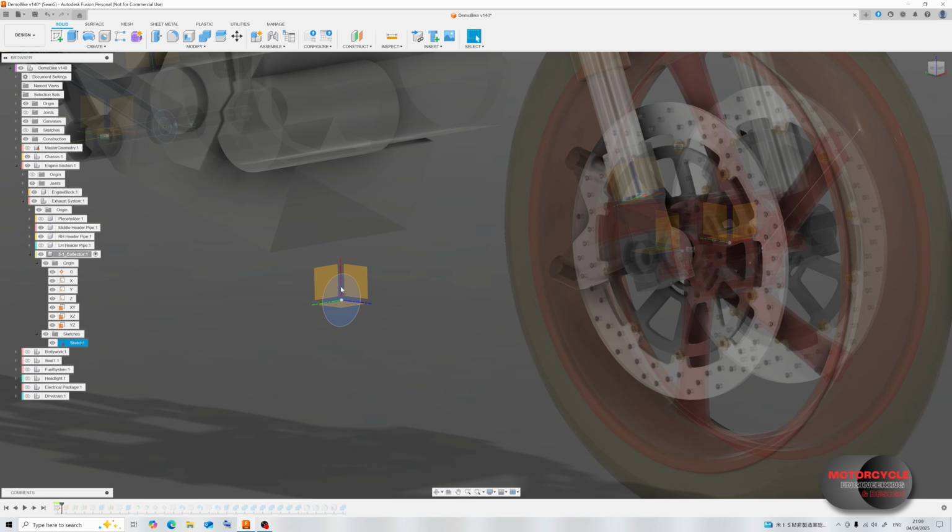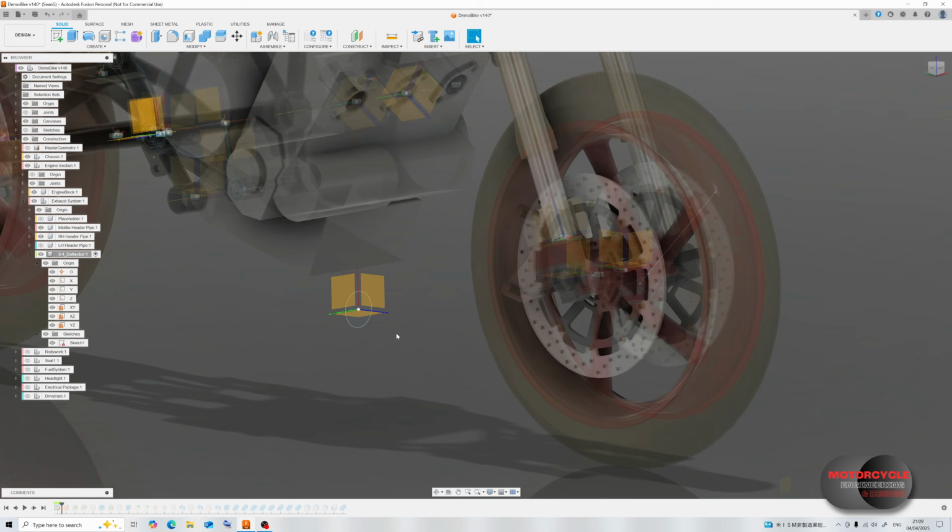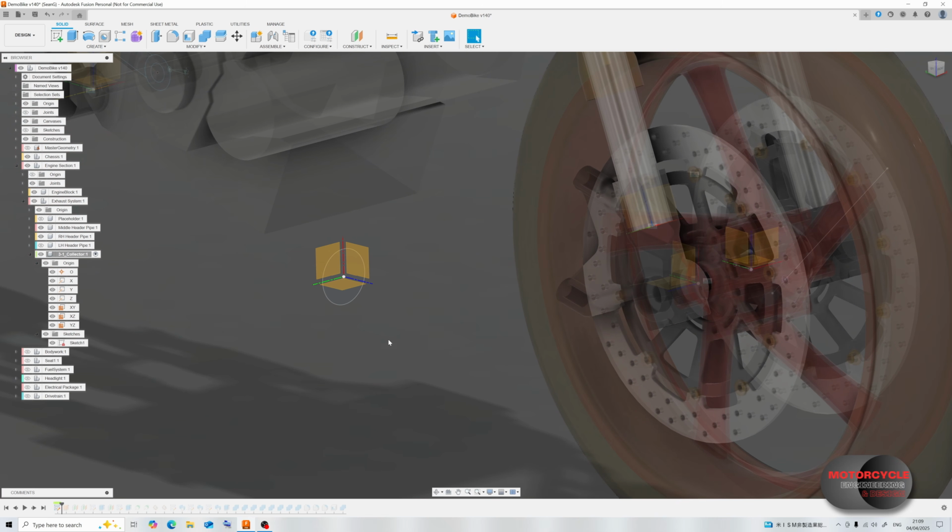the diameter of the collector should be larger than any single downpipe, but it doesn't have to be the same cross-sectional area as all three combined, because they're not all going to be discharging at the same time. We're not going to worry about choking the flow.